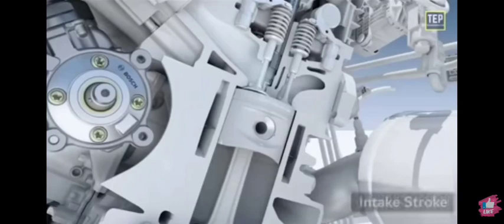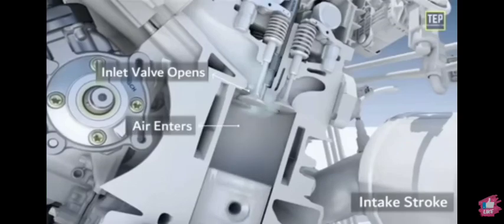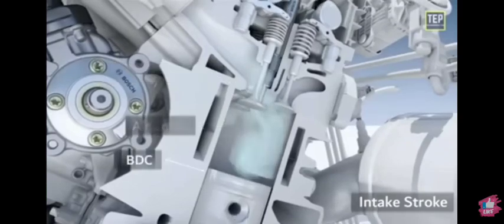Intake stroke. In the intake stroke, the piston moves down and the inlet valve is open, which allows air to enter the cylinder and fill the space. Then the piston reaches the bottom center and again starts moving up.